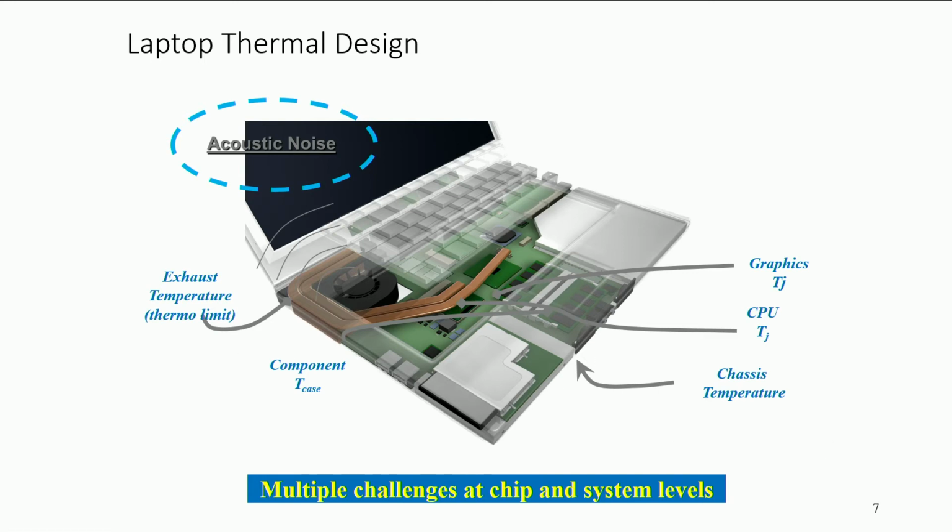So as this fan runs, it will suck in air from all these inlets that are available to us, including your connectors and all. They are all teeny mini sources of air inflow, air ingress. That air, when it comes in, flows over these components and cools them down. And as I was saying, traditionally this was good enough. However, now with more powerful memory, more functionalities and thinner laptops, these non-CPU components are also becoming challenging. I have to keep those other component temperatures also within limits.